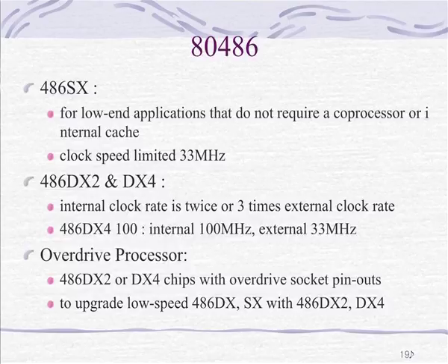Now, this is the block diagram of 80486. Again, we can see the various components of 80486, that is its registers, its ALU, its control units, and its 32 byte queue. It is using a 32 byte queue. At the earlier stage in 8086, we had only a 6 byte queue, and now in 80486 we have a 32 byte queue. So, the processing speed will be raised to a greater extent.